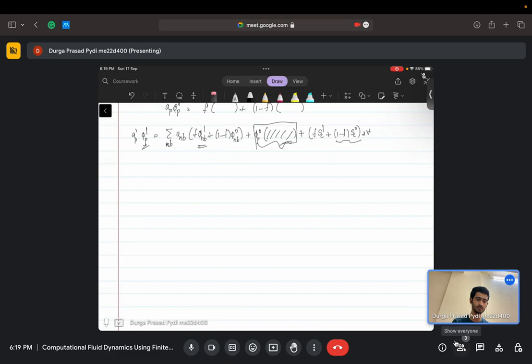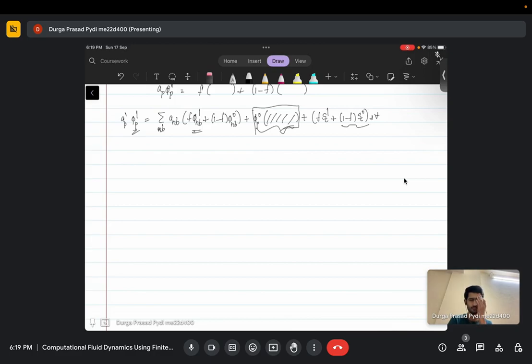Have any other questions? Okay, so let's say, for example, we are solving a problem. Right now we know structured and also unstructured mesh, right? In unstructured, we know it can be orthogonal or non-orthogonal. So which one would be closer to the actual solution? Because non-orthogonal involves secondary gradient and it doesn't stay bounded, but you can make it bounded using some relaxation schemes. So which one will be more accurate? Accuracy again depends on the profiles you have assumed, like linear profiles. Depending on your profile assumptions, all of them will be first order or second order accurate.